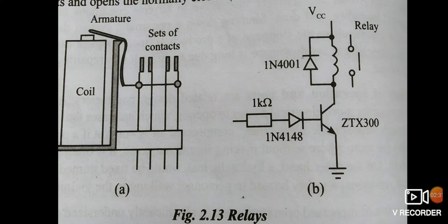They can generate a back voltage when the energizing current is switched off, or when their input switches from a high to low signal. As a result, damage can occur in the connecting circuit.